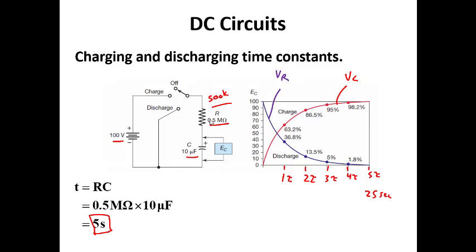And then we'd get our maximum current. 100 volts across the resistor, the current flowing in this circuit, I, is going to equal the voltage across the resistor divided by the resistance. So we get the maximum current right at the beginning. And then it's going to start to slow down. The current will start to slow down, and our rate of charging the voltage will also slow down.